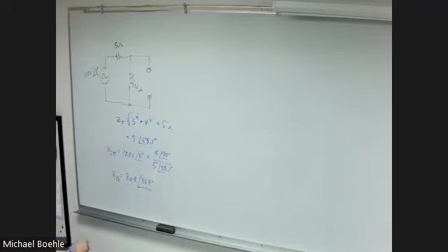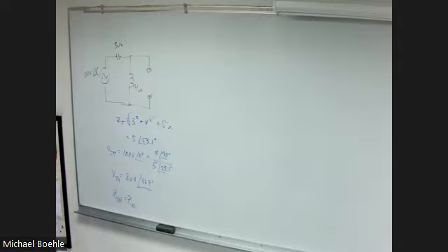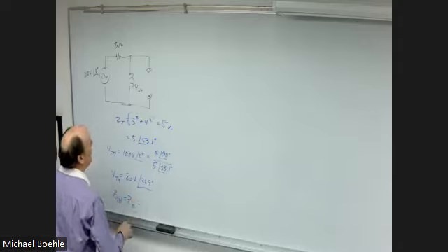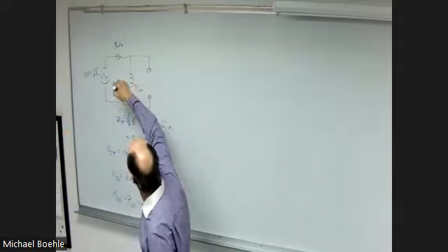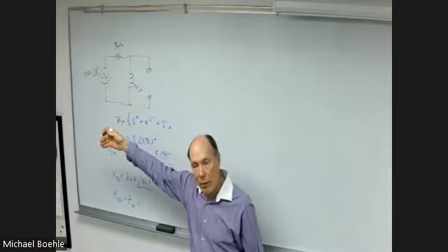Now, your Thevenin impedance, which is also going to be your Norton impedance for question number 34, will be, looking back in here, replacing that with a short, puts those two in parallel.